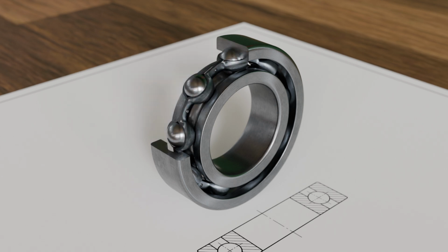If the rolling elements are balls, the bearing is called a ball bearing. Deep groove ball bearings are the simplest design, highly versatile, and therefore the most widely used. In this design, the balls roll in a semicircular groove in the inner ring and outer ring. These bearings are especially suitable for supporting radial forces, which is why they are also referred to as radial deep groove ball bearings. Due to the point contact between the balls and the raceways in ball bearings, relatively low friction losses occur, enabling high rotational speeds.